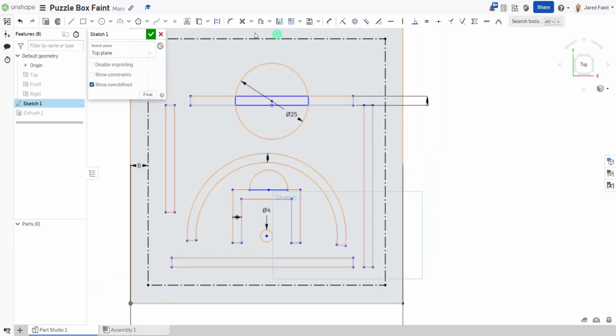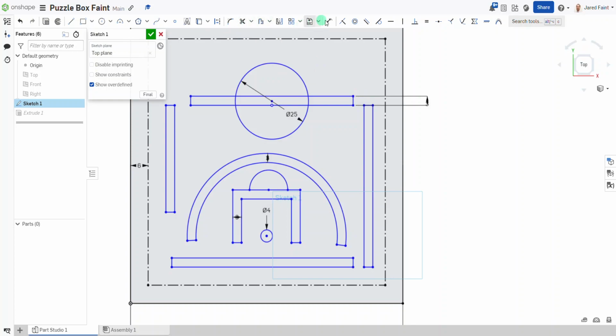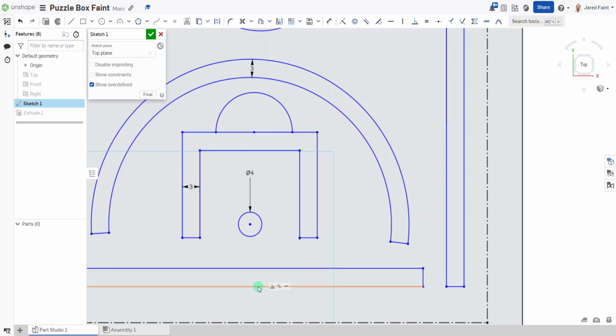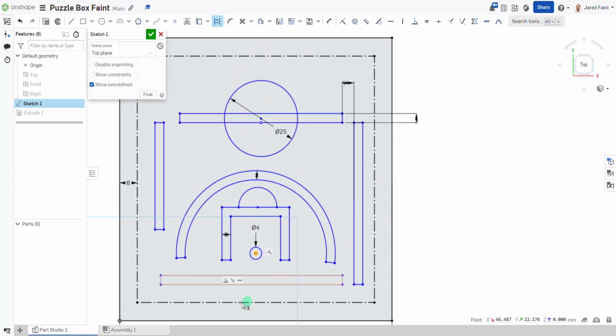If I then go and add a dimension here, I can then say how much of a gap I want there. So I can make that, all right, let's make that a 4mm gap. So there's some space. You can start then defining all the parts that I want to be dimensioned and where the middles are. So if I go onto this one, I can find there, and I can add it to the middle by adding that split line through again.